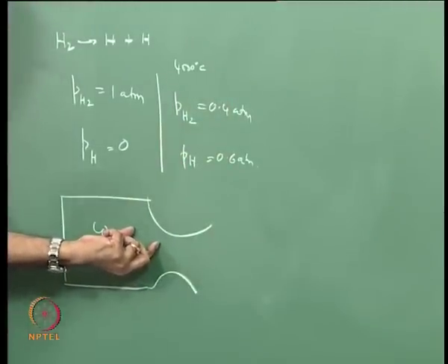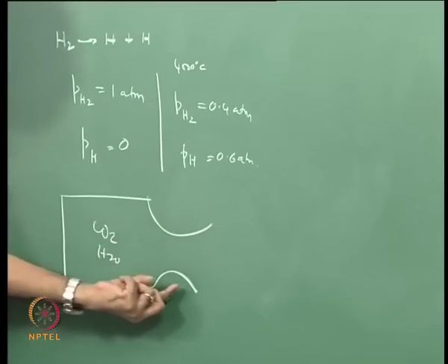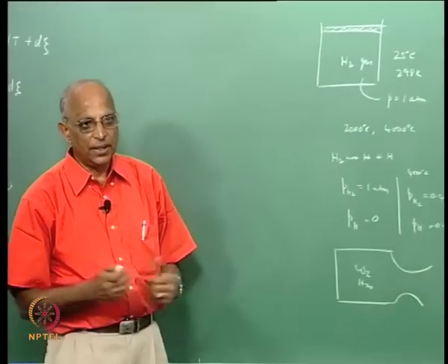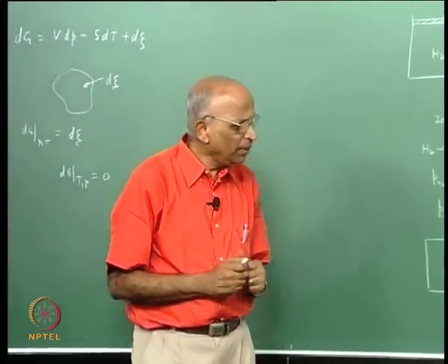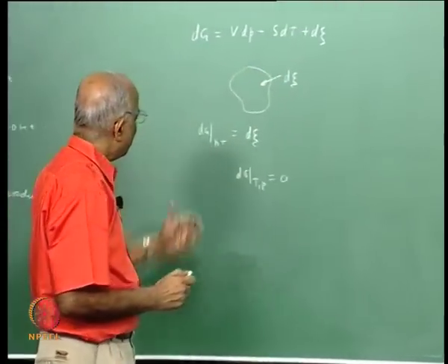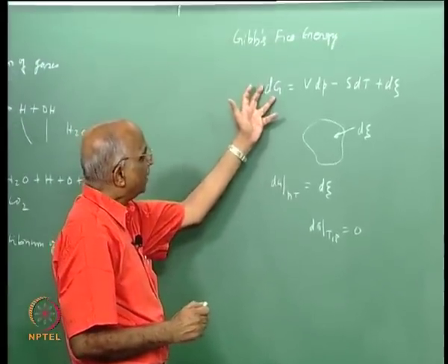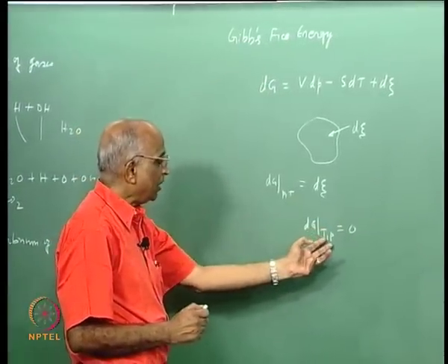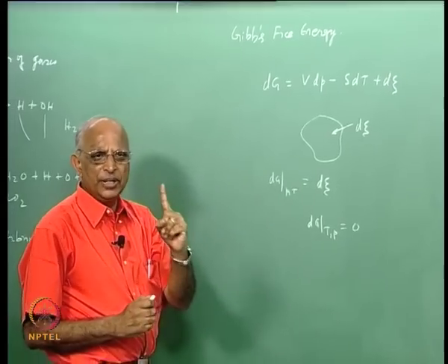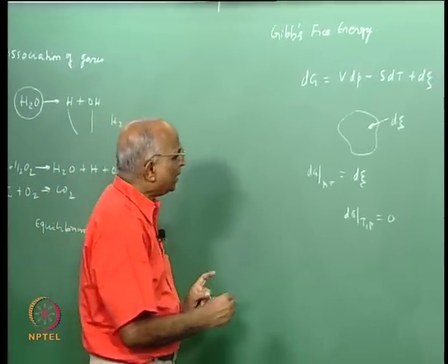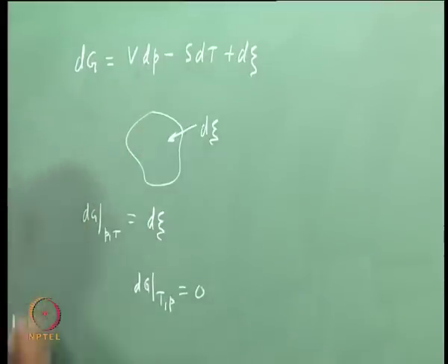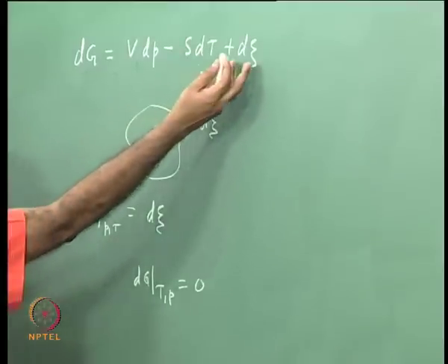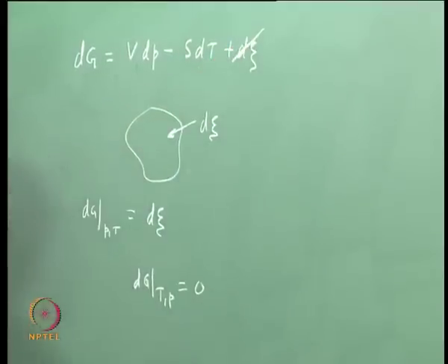But there is something else which is extremely important that concerns the flow in the nozzle, which I will come back to a little later. Is this clear, and why we are doing this problem? If this is clear, let us go back to this definition. We said dG is equal to 0 at constant temperature and pressure for a single medium, for a single species. Now I wrote this dG as dG is equal to VdP minus SdT, and I am considering this, maybe let me forget about the equilibrium part, maybe some non-PDV type of work being done.